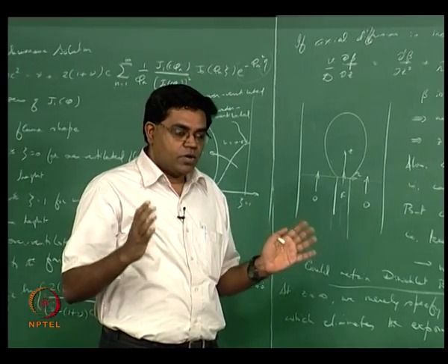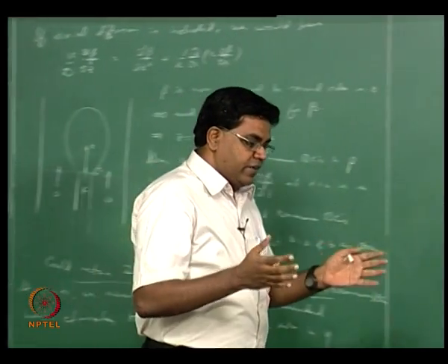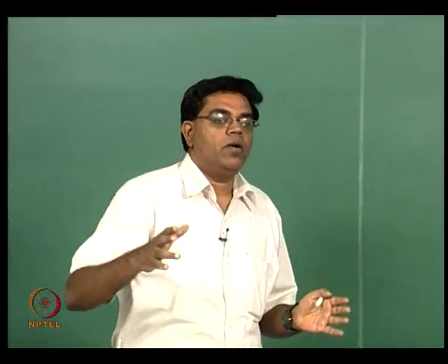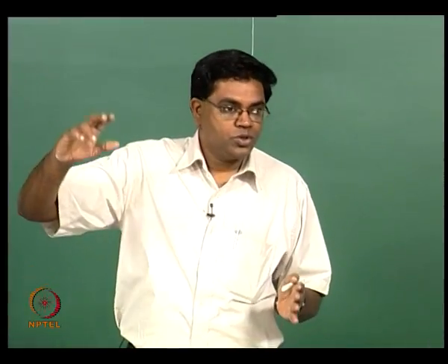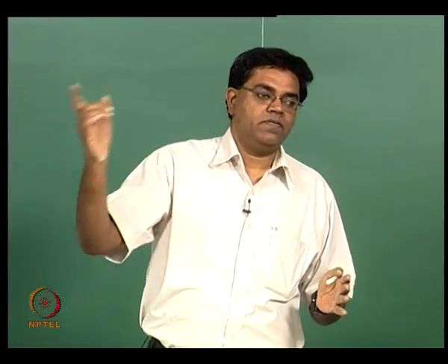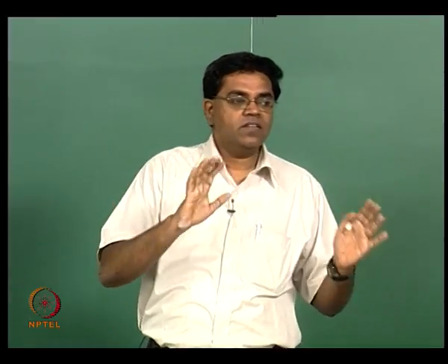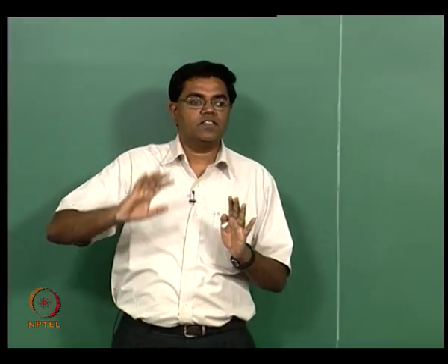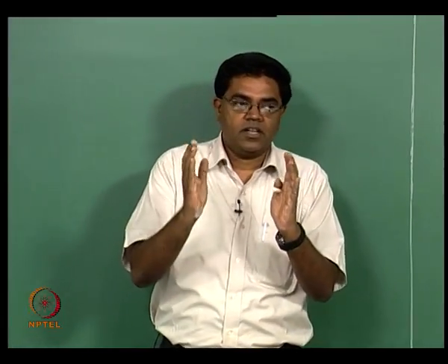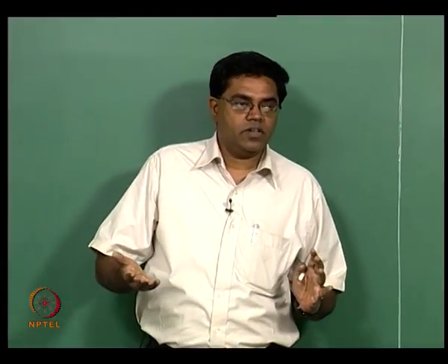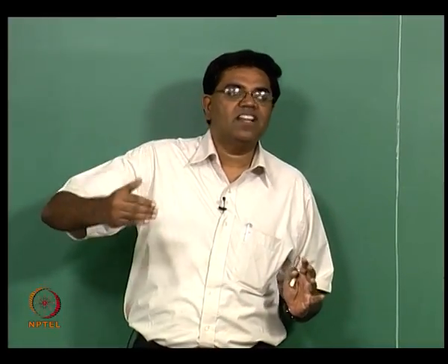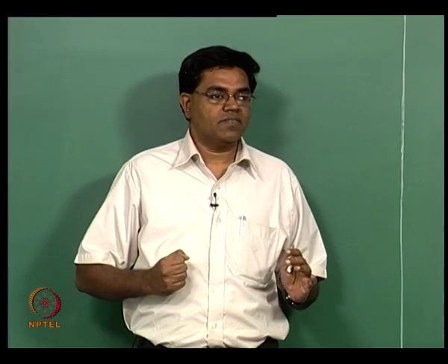So this is a problem where the convection could predominate axial diffusion but balances radial diffusion. Alright. So the balance between radial diffusion and convection is the centerpiece of this, but alongside at low convective effects you could have a significant contribution from axial diffusion as well.